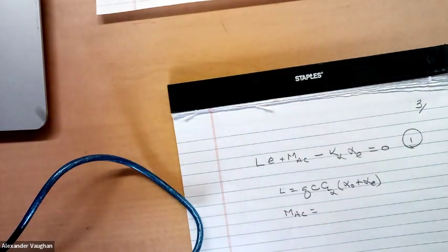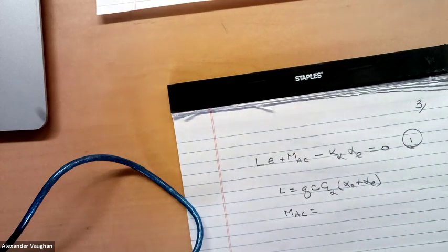We set it up that way. We looked at the pressure distribution, we computed the moment, and we found the place along the airfoil where the moment about that particular point doesn't depend on the angle of attack. And we define that to be the aerodynamic center. It's a convention. We don't have to do that, but that's what most people do. So that's what we're going to do.